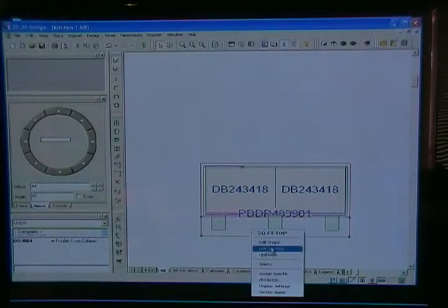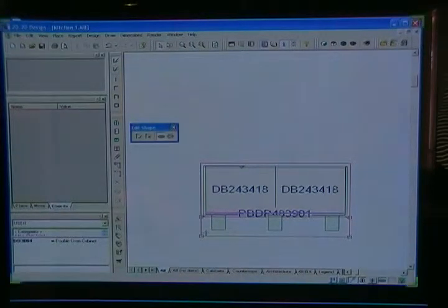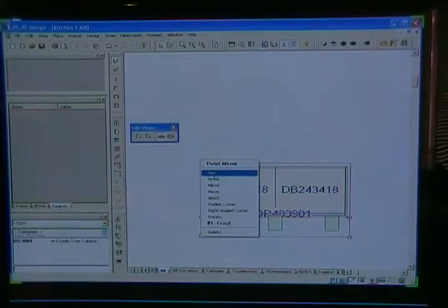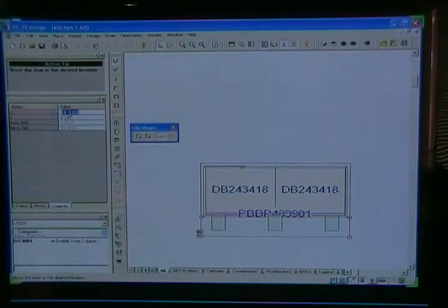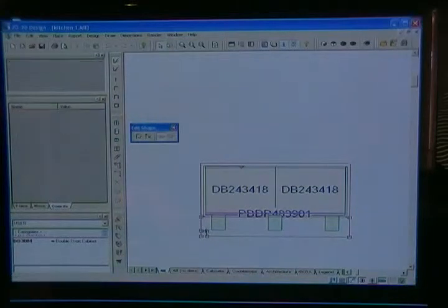I'm going to right click on it and go to edit shape. Now we're going to edge out the corners, and we're going to radius the end of this to have a 5 inch radius. How are we going to do this? We're going to right click into the first corner and select notch, because this is what's going to give me the option to notch out the square. Instead of doing it by eye, I'm going to use my X and my Y factor on the left hand side in the edit box. So I'm going to type in 2, tab to change the field, and then type 2 again, and then press enter. And notice now I have a notch on my countertop.